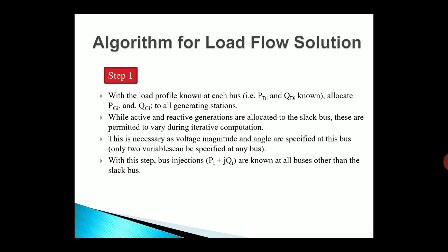First, step 1: with the load profile known for each bus, PDi and QDi are known. What is the load profile? It is, for every bus, what is the load connected to that bus? So we are talking about load, which becomes the real load and the reactive load. The real power load is PDi, the reactive power load is QDi.